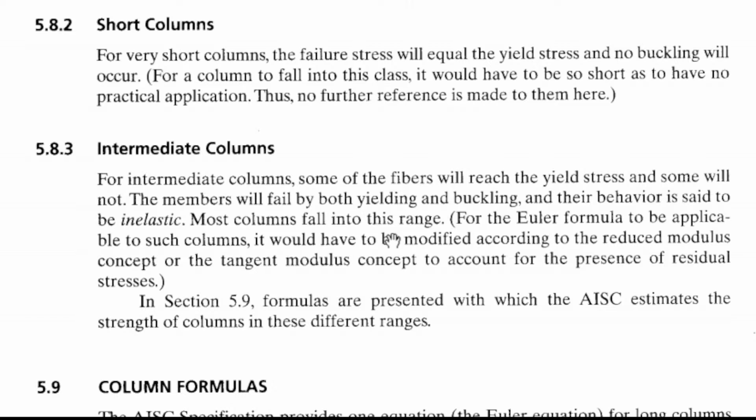For the Euler formula to be applicable to such a column, it would have to be modified according to the reduced modulus concept or the tangent modulus concept to account for the presence of residual stress.